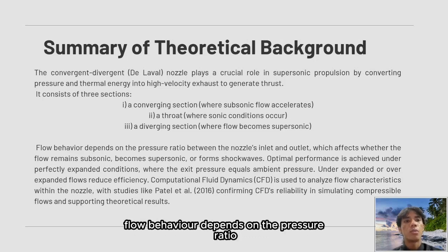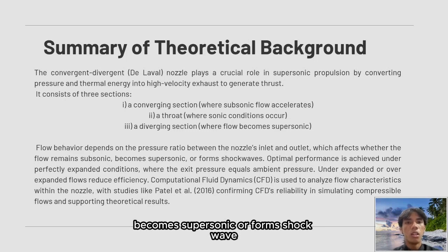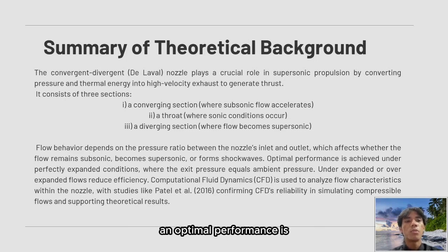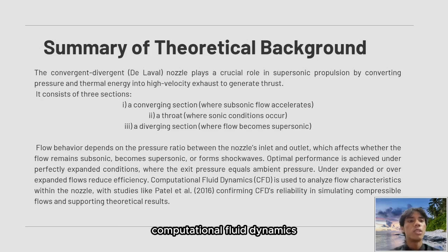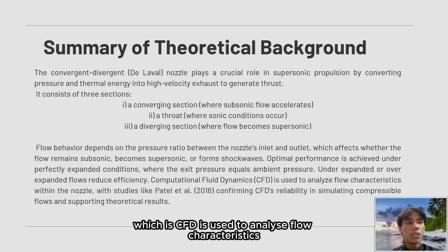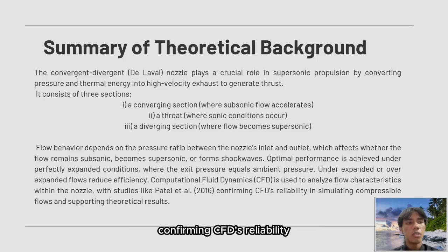Flow behavior depends on the pressure ratio between the nozzle inlet and outlet, which affects whether the flow remains subsonic, becomes supersonic, or forms a shockwave. Optimum performance is achieved under perfectly expanded conditions where the exit pressure equals ambient pressure. Underexpanded or overexpanded flows reduce efficiency. Computational Fluid Dynamics, or CFD, is used to analyze flow characteristics within the nozzle, with studies like our journal confirming CFD's reliability in simulating compressible flows and supporting theoretical results.